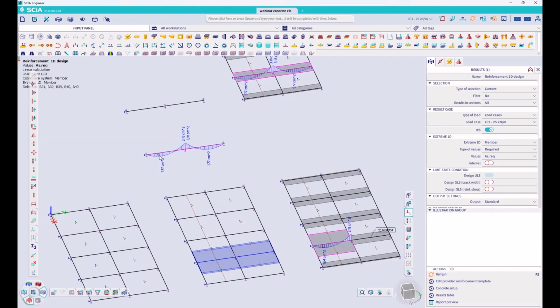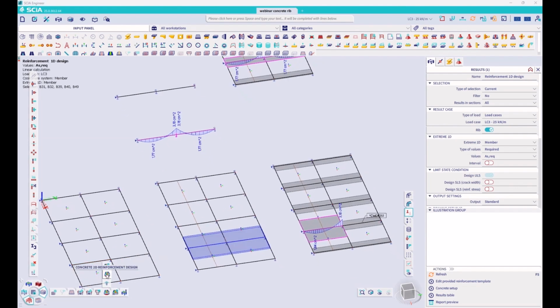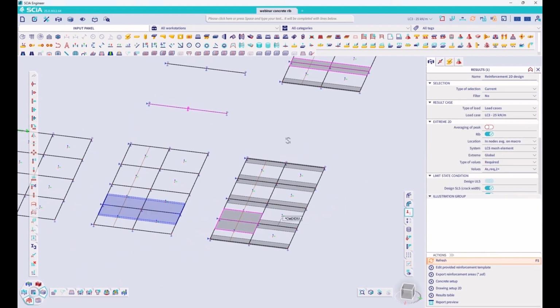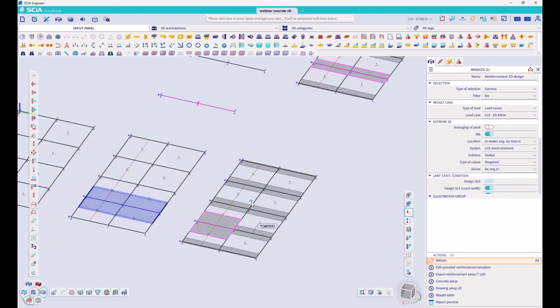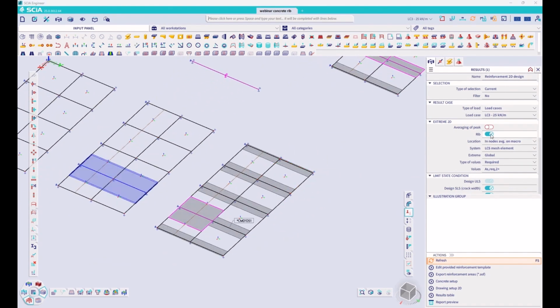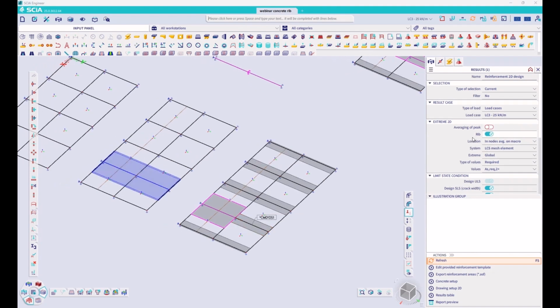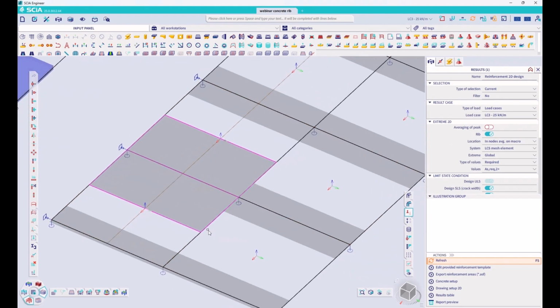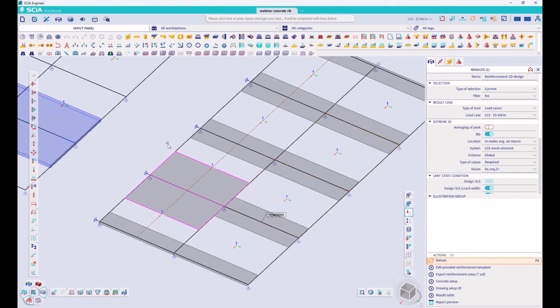This is also quite handy if you take a look at the 2D reinforcement. So if I take a look at a concrete 2D reinforcement design, there's also this option rib that all of a sudden pops up if you take a look at the reinforcement 2D design. And by clicking this option, you're basically telling SCIA that you took into account the forces in the plate for the calculation of the rib. So I'm telling SCIA, okay, for this rib, I took into account the forces that fall in this zone, and you don't need to put in reinforcement in the plate itself.